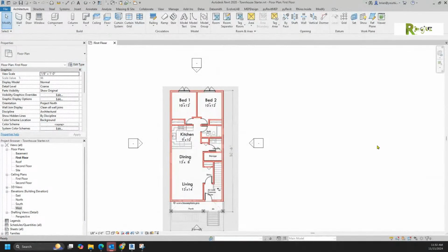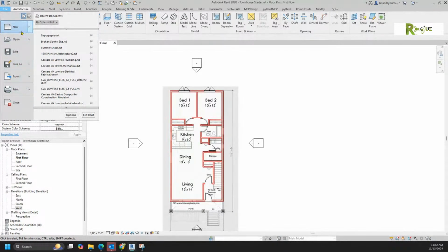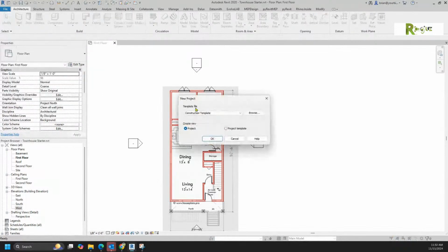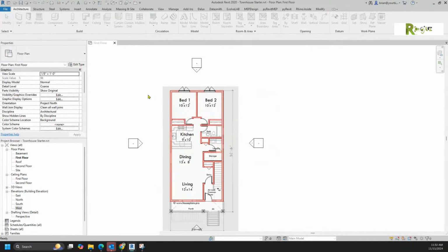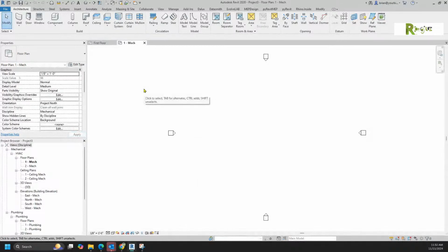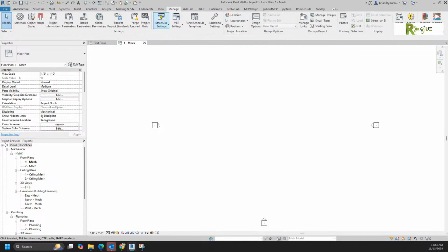All right. Everybody open up a mechanical file. Maybe Mike can try to explain the problem he was having. I was trying to get flanges only at the end of piping where I was placing valves into the line or system, and you can toggle through on your pipe type and add the flanges. But if you do, you get a flange on your elbows, your T's, you name it, it gives you flanges on everything. And if you try to delete those flanges and rejoin the pipe, it puts them right back on there.